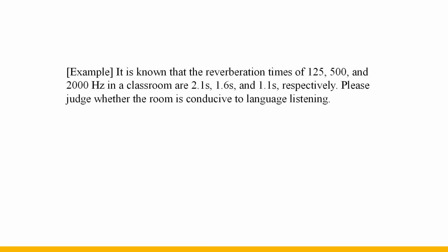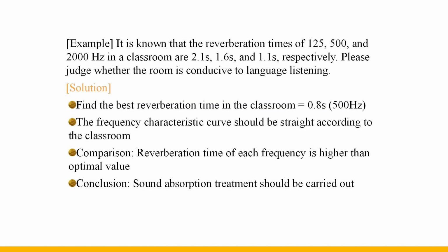The reverberation times of 125, 500 and 2000 Hz in a classroom are 2.1 seconds, 1.6 seconds, and 1.1 seconds, respectively. Please judge whether the room is conducive to language listening. According to the best reverberation time chart in the classroom, the best reverberation time at 500 Hz is 0.8 seconds.